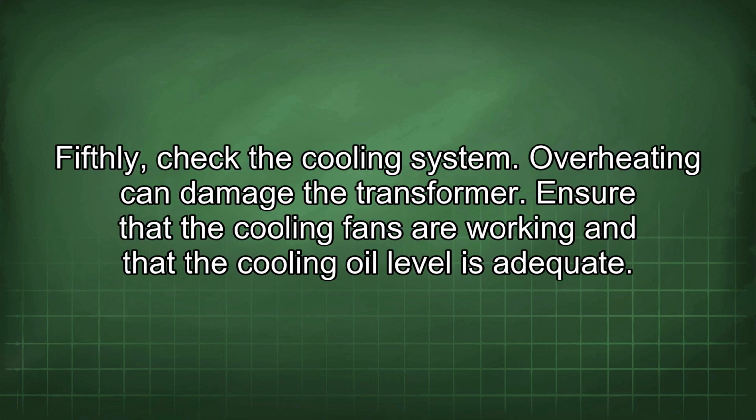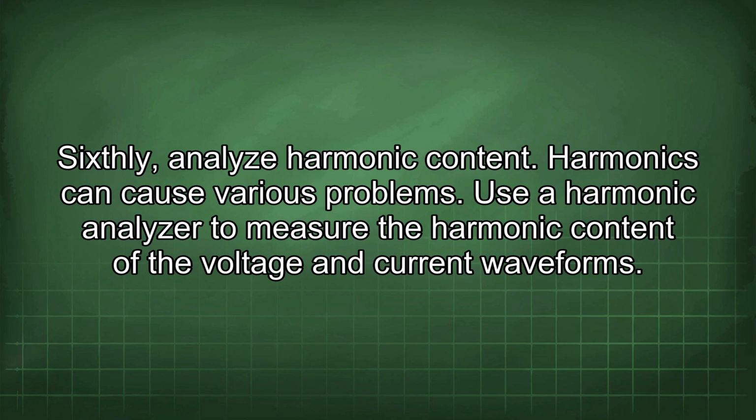Fifthly, check the cooling system. Overheating can damage the transformer. Ensure that the cooling fans are working and that the cooling oil level is adequate. Sixthly, analyze harmonic content. Harmonics can cause various problems. Use a harmonic analyzer to measure the harmonic content of the voltage and current waveforms.